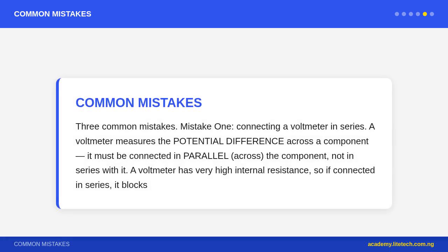Question 2. State the difference between a fuse and a circuit breaker. A fuse is a short wire that melts permanently when excessive current flows. It must be replaced after blowing. A circuit breaker, MCB, is an automatic switch that trips or opens when overloaded. It can be reset simply by switching it back on. MCBs are more convenient and safer for frequent tripping situations. Fuses are cheaper and suitable for one-time protection.